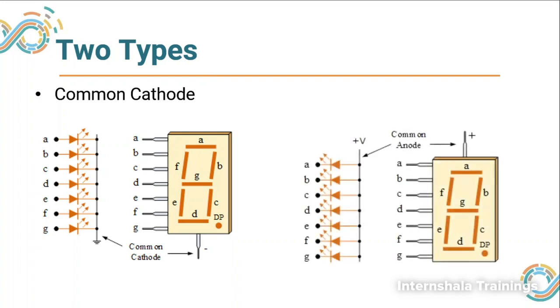The second one that we have is common anode. Anode means P side, and if we have to keep it common, we will keep it common at 5 volt or logic 1. Now if I want to glow these LEDs, let us say I want to glow LED A. If I give 5 at A, the potential difference across the two terminals is going to be 0.